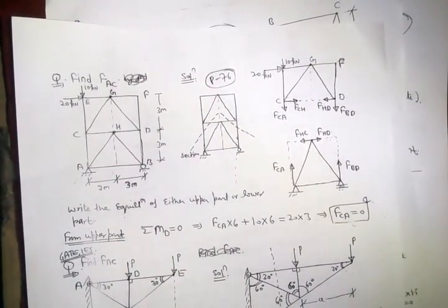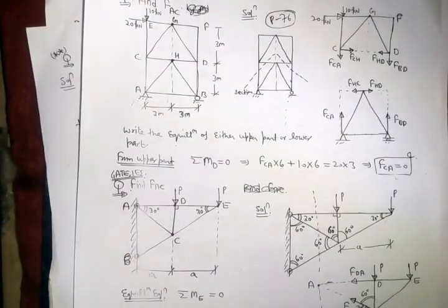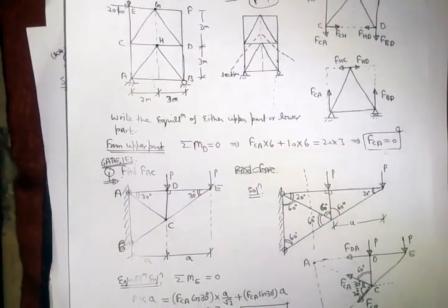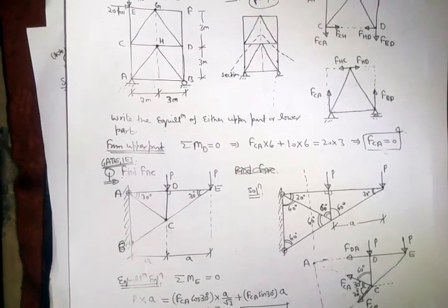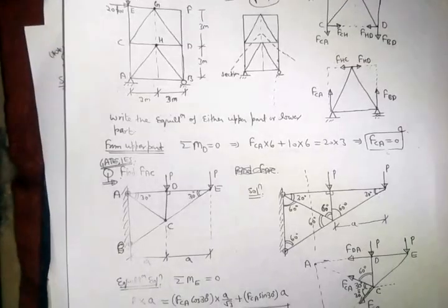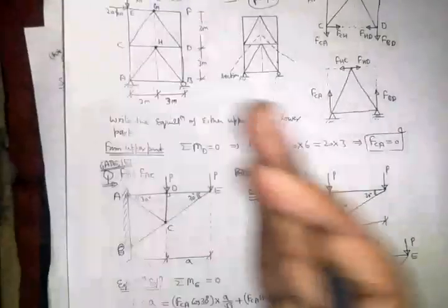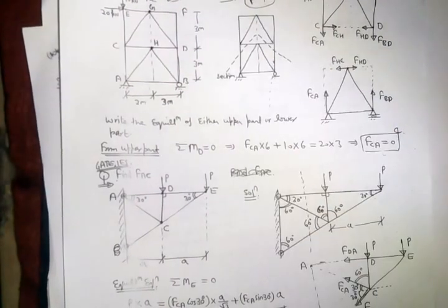Next question is this. This same question was asked in GATE and IES many times. It asks to find the force in member AC, right? So always in this question, remember, we will make the cut here, right?